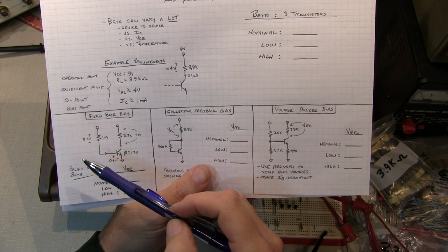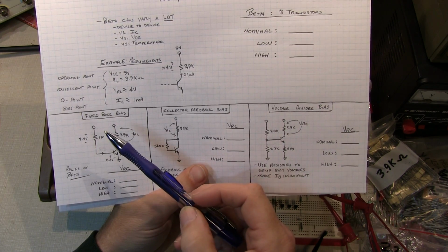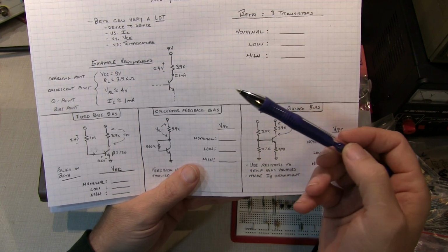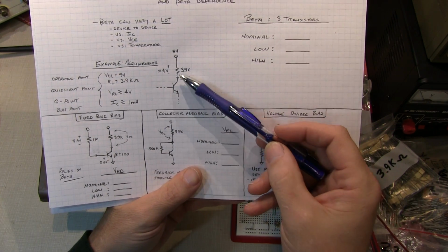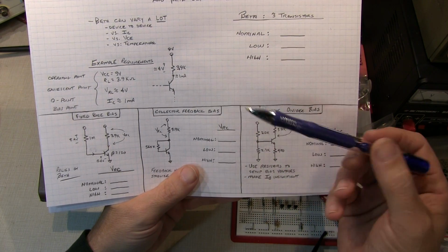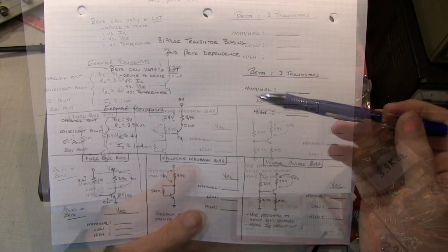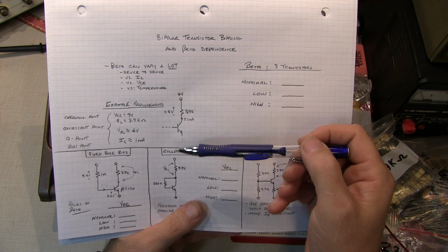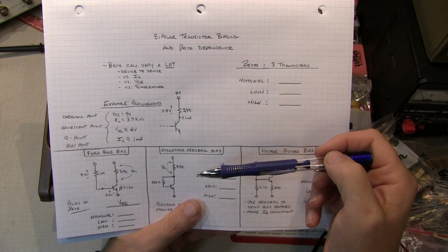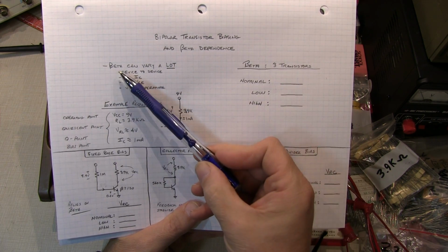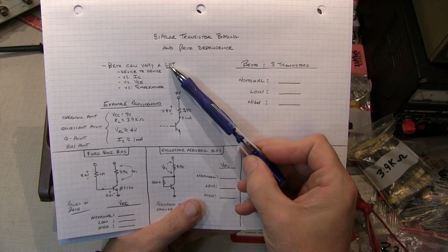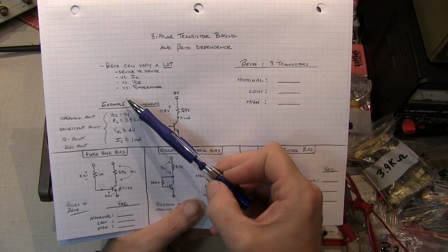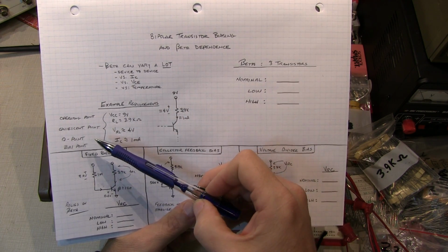When the transistor is used as a switch, it's not typically that important. But when it's used as an amplifier or many other applications, the bias point is going to control the performance of that circuit, so it's important to have a bias point that is predictable. Now, many people, when they start to set up the bias point, will start considering beta, or the current gain of the transistor, and use that when trying to figure out how to set up the bias point. The problem with that is that beta can vary a lot, from device to device, versus collector current, versus collector emitter voltage, and even versus temperature.